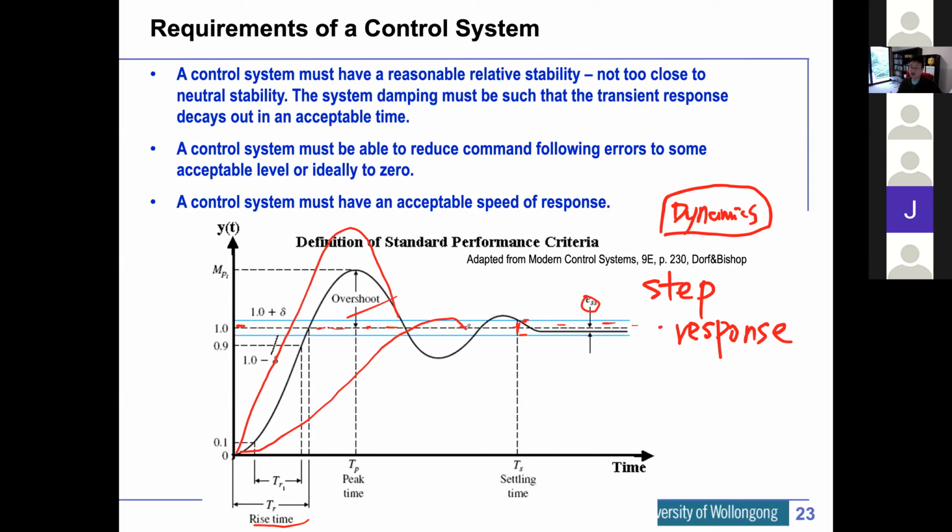So when you do control, what you do is you change the features of this dynamic system. You're putting more poles and zeros into the system so you'll be able to get better performance. But you can't really ignore the physics here. You won't get a perfect system where input equals output perfectly. So you have to make a trade-off in your situation.